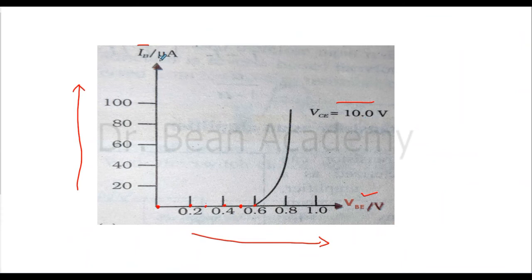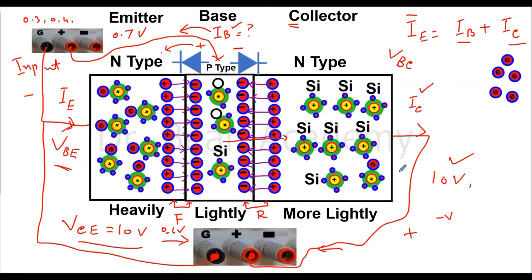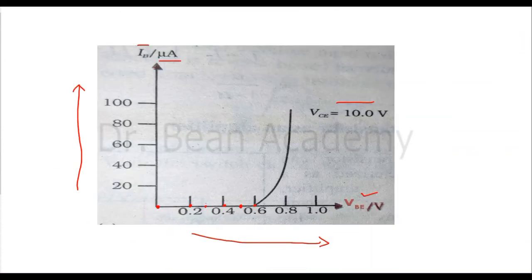This current is in microampere. So remember that unit, because next when we see the output characteristics of this setup, you will see that this current is nothing when we compare it with the current coming out of the collector, this IC, when we measure it in the output, because now we are only considering the input characteristics. So just remember the unit, don't just see the number here, like it is 180.